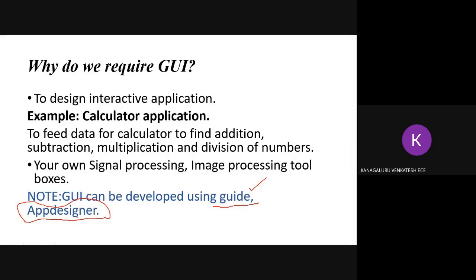Whereas with App Designer, by default they give some components. You can make use of those components. Simply you can drag those components and release them in the environment, and then you can use them. Okay, I'll show you both so that you can feel it visually. By looking at it, you can feel whether you can go with GUIDE or App Designer. So with respect to programming, App Designer is user friendly.